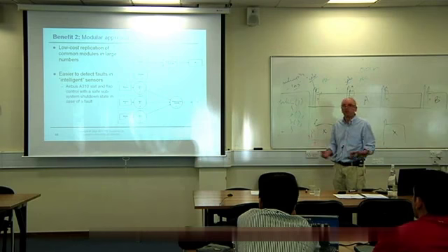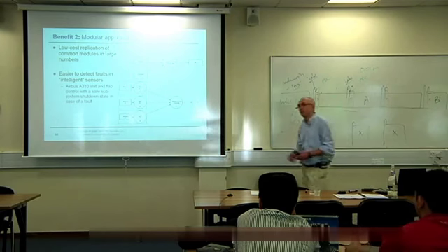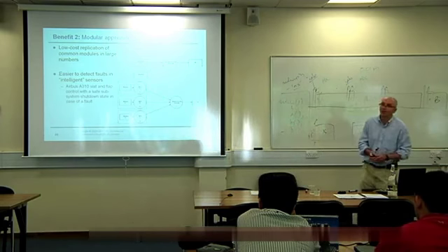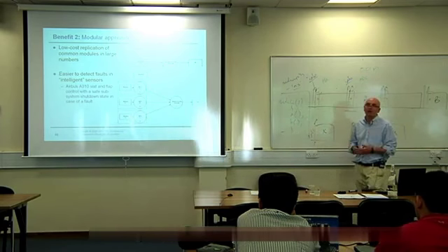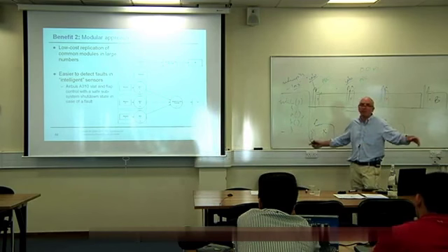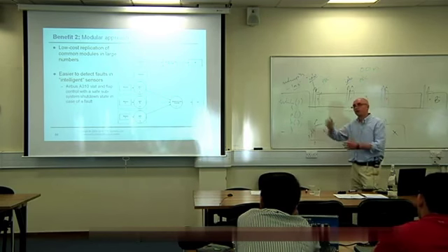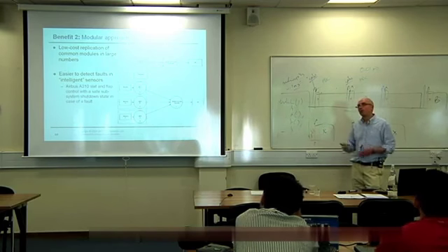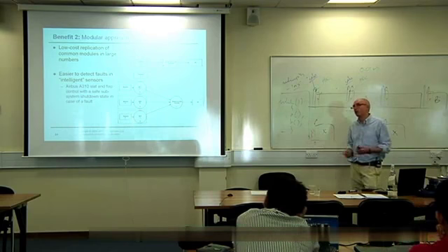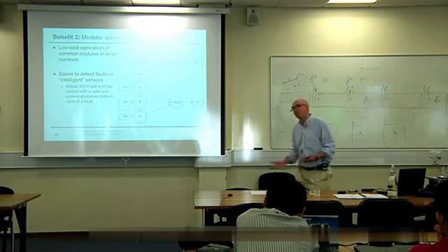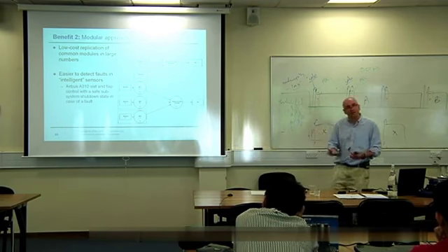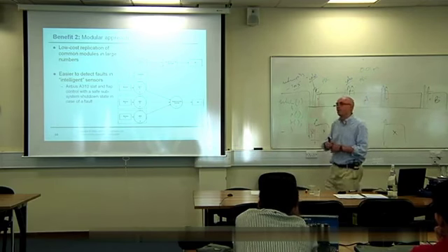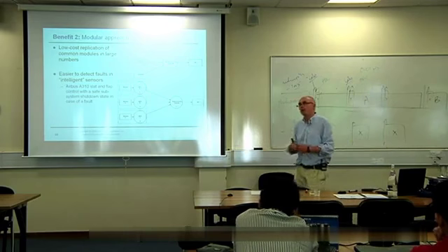Straightforward. Okay. So if you make the system intelligent enough to know that it's lost control, lost communication with the main part of the aircraft, then at least you can have your intelligent subsystems. If they're dumb and they're just told to turn the rudder to a particular angle and that's all they can do, you're in trouble. But if they're more intelligent, quote, unquote, and you cut the cabling, then you can set them up so that they automatically detect lost communication, get into a fail-safe state, and then we've got a better chance of getting that plane onto the ground.